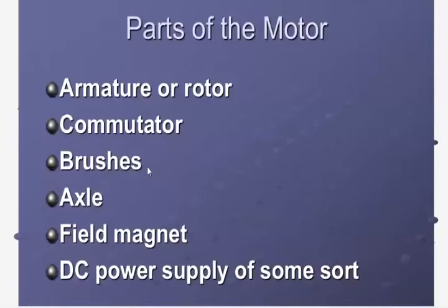But graphite is also a good conductor of electricity, so being in contact with the commutator keeps continuous electrical contact and supplies electrical energy to the coil, that is converted into mechanical energy.